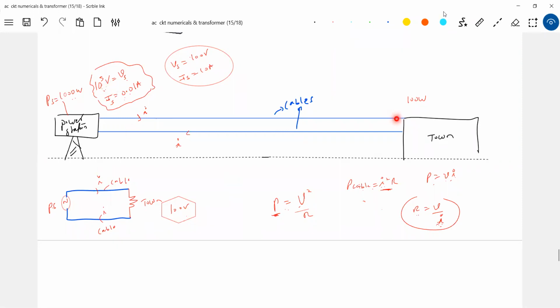So what I do, I will step it down from 10 to power of 5, from 1 lakh, to around 10,000. From 10,000, I'll convert that into 1,000. From 1,000, I'll convert into 100. I'll step it down. So therefore, what is the requirement now? To minimize power losses due to transmission in the cables, I should transmit the AC signal with high voltage and low current.